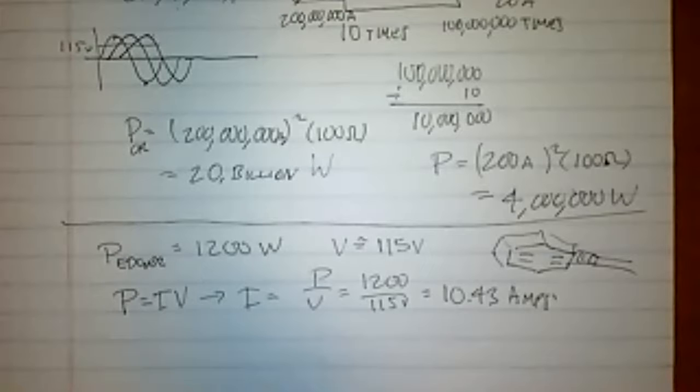Also, if you have a generator, like I got a generator for hurricanes and snowstorms, and it's rated up to 4,500 watts. That's kind of nice, because now I know my TV runs 120 watts and my refrigerator runs 800 watts. As long as those numbers don't add up to anywhere close to 4,500, then I can run that.